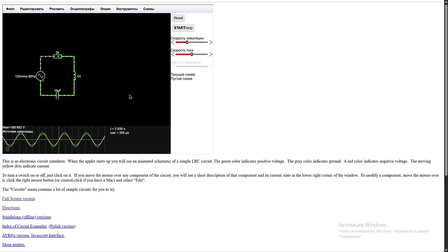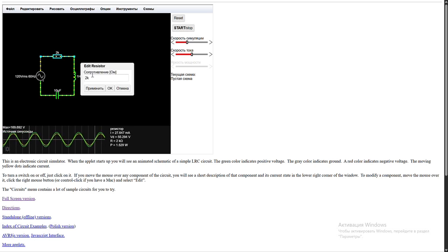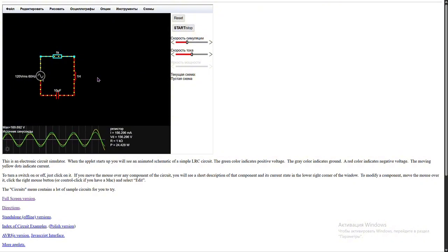However, look at the position on the frequency axis. The peak didn't move, it's still exactly at the same place, the 200 kilohertz in our problem, but in the simulation it's 60 hertz, so it doesn't matter. This confirms our abstraction step. Let me bring it back so you can see that it remains the same. Look at the green line, and you can see it remains the same.